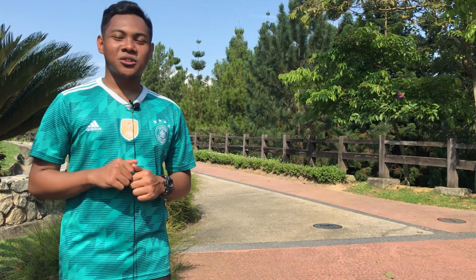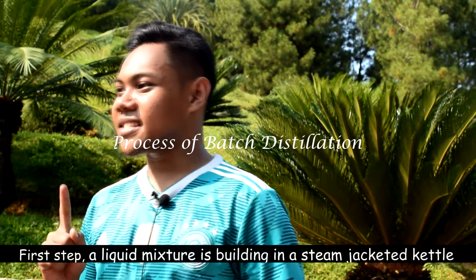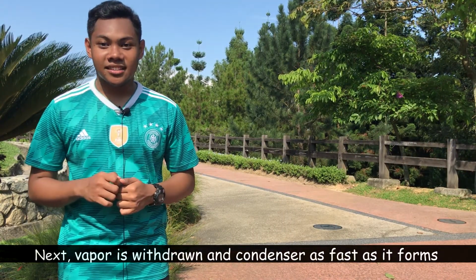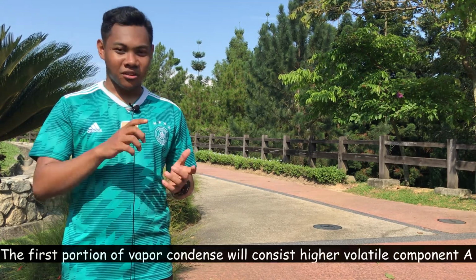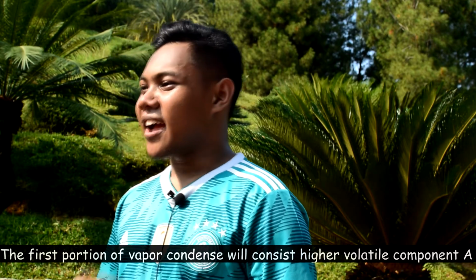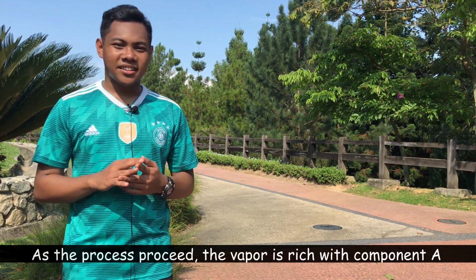Batch distillation is also known as differential distillation. Only one vaporization stage is involved. For the process of batch distillation, the first step is that a liquid mixture is boiled in a steam-jacketed kettle. Next, the vapor is withdrawn and condensed as fast as it is formed, in order to prevent the liquid and vapor from reaching equilibrium. Then, the first portion of vapor condensed will consist of the higher volatile component A. As the process proceeds, the vapor is rich with component A.